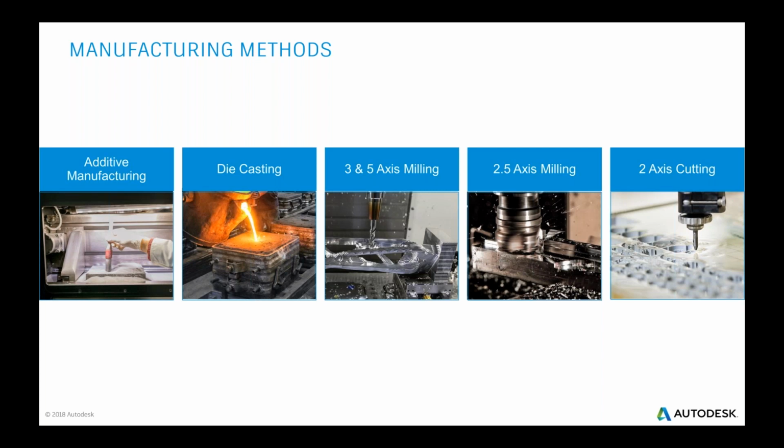So in many situations, I tend to tell people, feel free to include an additional manufacturing method just so that it can help give you a better understanding of how that part behaves and where mass is needed to fulfill some of your other requirements, because it might give you some other insights into your design.